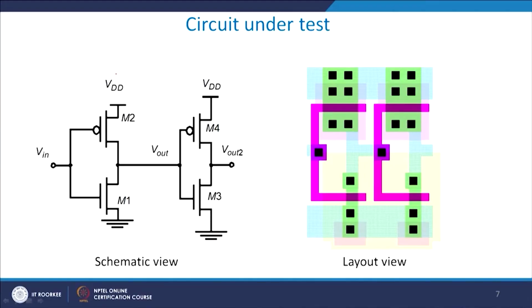So look at the second test. As you can see I have got two CMOS inverters driving each other. Let us suppose the first one is Q1, and the next one is Q2. So Q1 is driving Q2, and as you can see here, very interestingly, you have a contact here. This contact is this one, and when the poly layer and the metal layer cut, this is basically your MOS device.